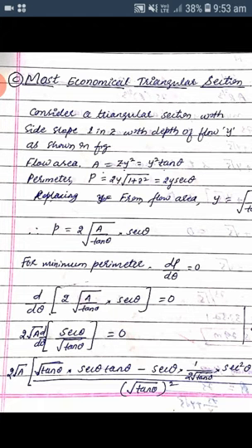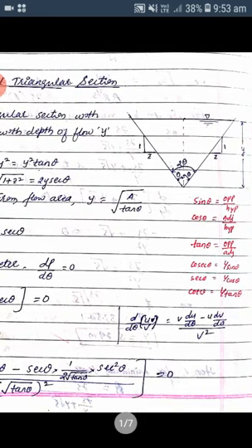But this is in terms of depth of flow. The area of flow written here is in terms of depth of flow. But in terms of trigonometrical function, the flow area becomes y square tan theta. How does this tan theta come? Again, look at the figure. In this figure, the angle subtended at crest level is 2 theta. This angle is theta, and this angle is theta.